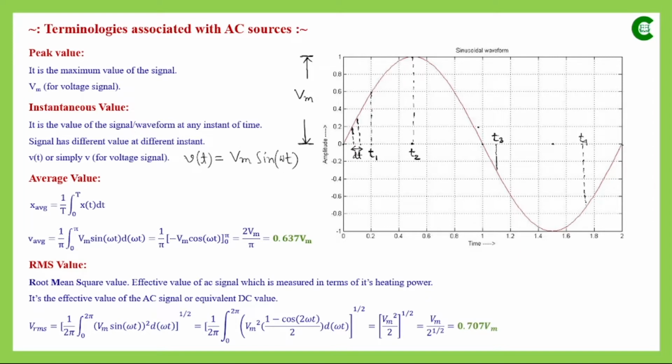In this graph the signal is varying with respect to time, which is the linear variation of that signal, but at the same time the signal also varies angularly from its reference line. When an AC signal linearly completes its time period, which we represent by T, angularly it will always complete a 2 pi radian angle.